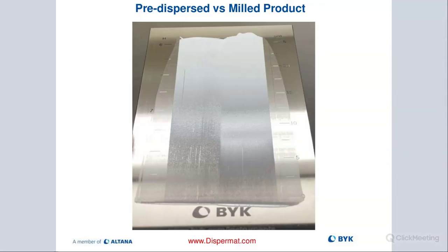And then on the right, you can see we continued, moving from a dissolver over to a bead mill, and then we were able to get a much better product, a much finer particle size distribution and finer particles. So it's really important that dispersing or pre-dispersing is only one part of the process, and milling is critical if we want to have really the best performing and best looking product.